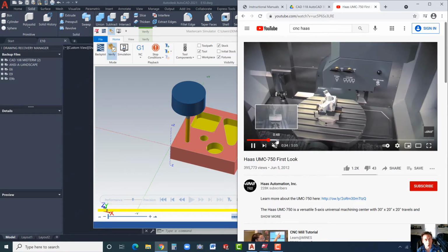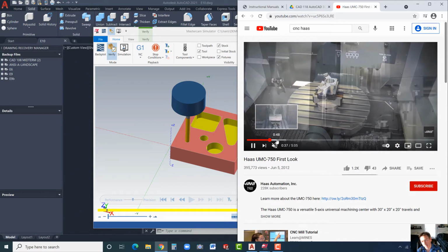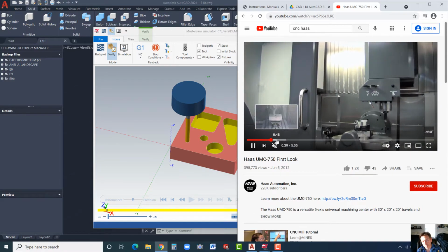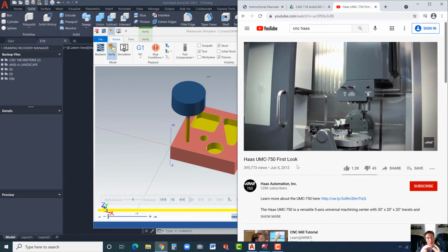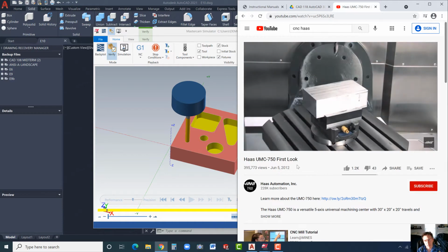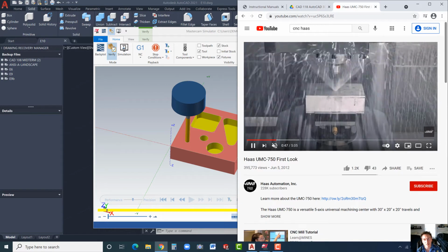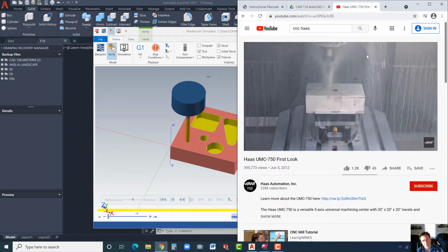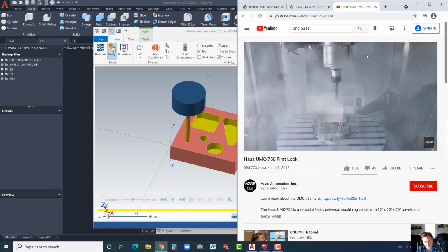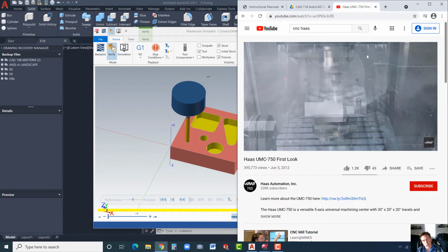We're going to do what they call 2.5 axis, or it's kind of more like an end of 3D, whereas 5-axis, there's a lot more movement that's available. Like you can see, that's rotating and spinning. And that's jets of coolant that are flowing down there as it drills. And see how it's peck drilling? It's going in and out, and that helps break the chips.